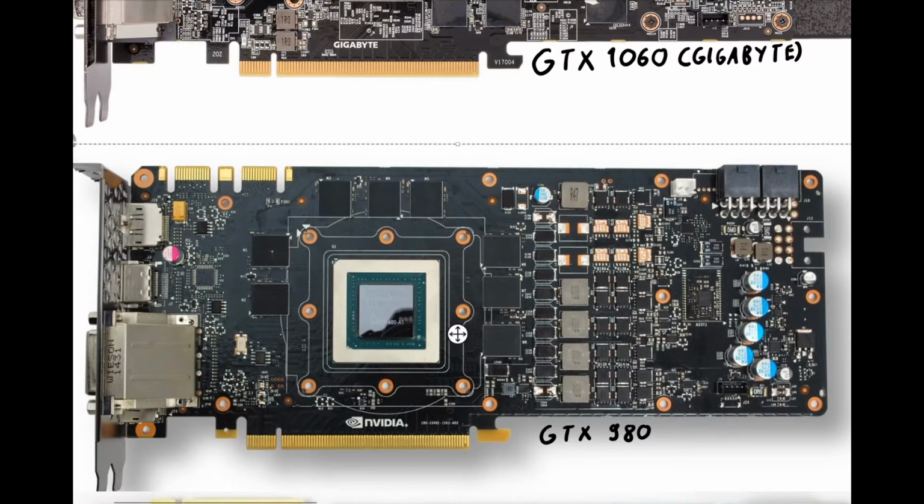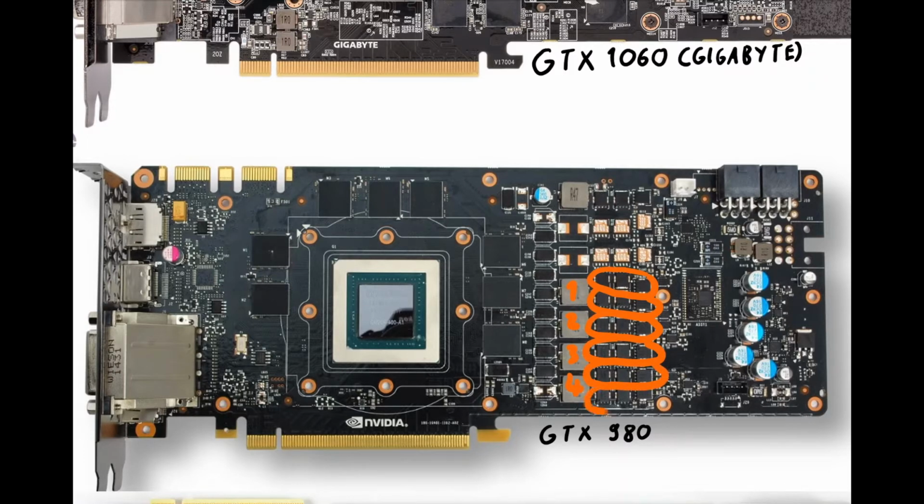A good example of this is here. You have 1, 2, 3, 4 inductors, but if you count the Mosfets, because I've already told you that you have 3 Mosfets in one phase, you end up with more than 4 phases. I don't completely know this VRM, but there's basically just one way it would make sense, because this VRM is actually a 6-phase. It's just using 4 inductors. So on the outer inductors, those 2 phases which are so tightly together share the inductor over on the left side. So that's one way you can have more VRM phases than you can count.